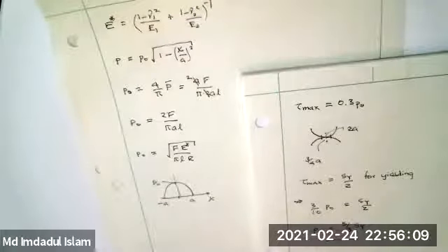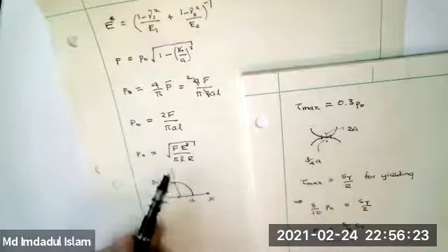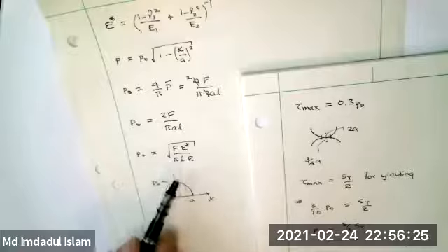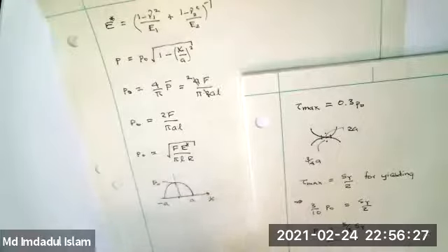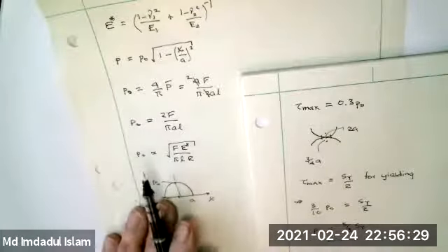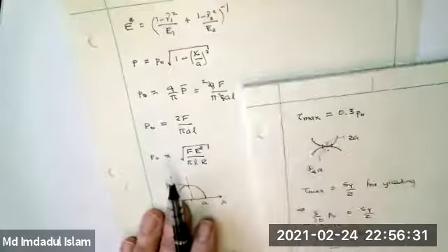And so this means when you design things, you can have stresses that exceed the yield strength and not have fatigue problems. It's okay. Moreover, because these contact stresses depend upon the square root of F, you can actually increase your load quite a bit before you get yielding. And so this is all a little bit counterintuitive. That's one of the reasons for studying it.